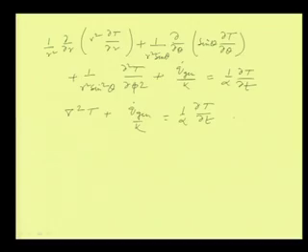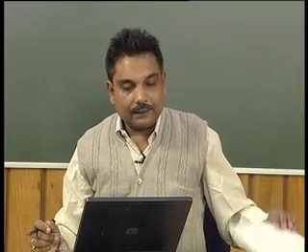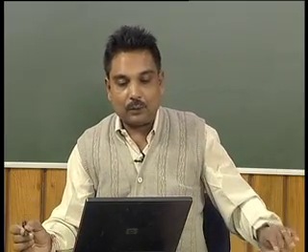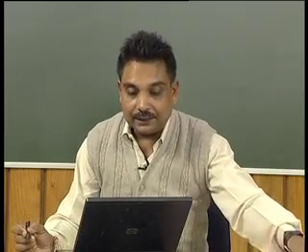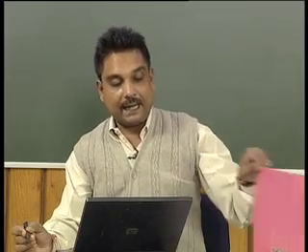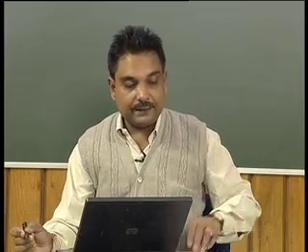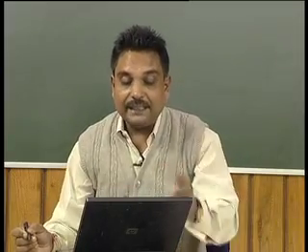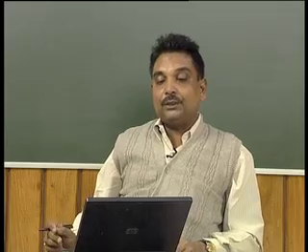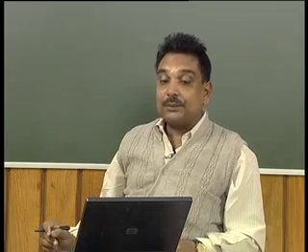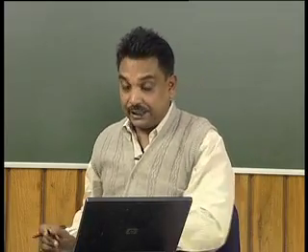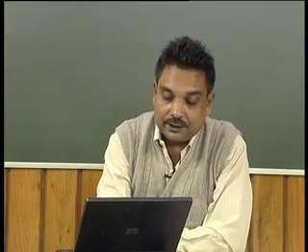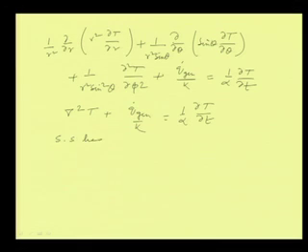From there we can see that this general heat conduction equation, or the Fourier field equation, can have different assumptions, or by applying different constraints to this equation, we can simplify it into different forms. For example, if we say that it is a steady state operation, a steady state process, steady state heat transfer.